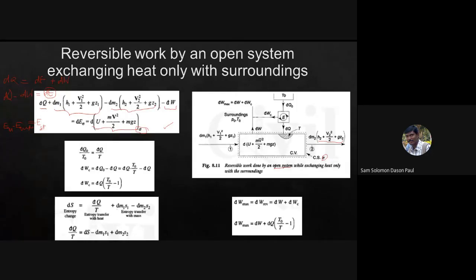Okay, and we know this is a reversible engine, this is a reversible heat engine. So according to the absolute thermodynamic temperature scale, we know that dQ naught by T naught is equal to dQ by T, and that is applicable only for a reversible engine. You can see the reversible sign here, E followed by a circle with two arrow marks. So this shows that it is a reversible engine. Because it is reversible, we can write dQ naught by T naught equal to dQ by T.